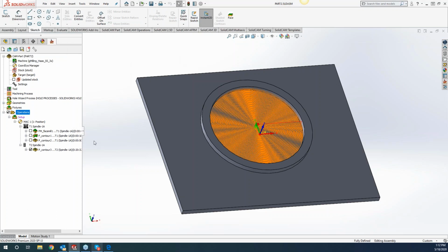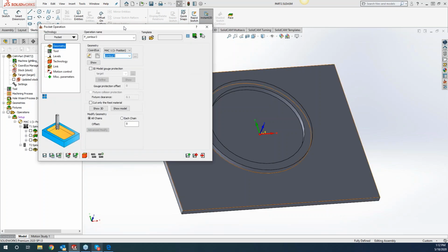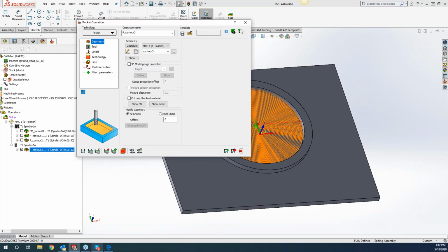Okay. Now, along that same lines, some of you do not like when I do a save and calculate. I didn't change anything here, but once I save and calculate, it automatically turns on my toolpath. Some of you guys love it, some of you guys hate it. It gets to be a lot if you're calculating everything. So I'm gonna show you 2 different things here. I'm gonna show you how to turn that off as well as how to do a quick turn off of all your toolpath that's in there.